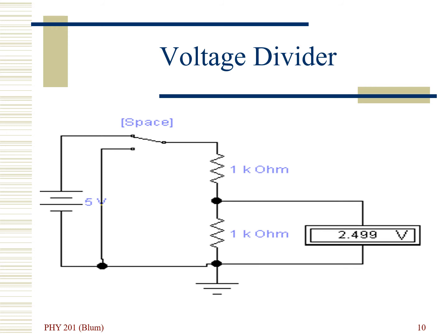We have a 5-volt battery, so we're considering 5 volts to be high and 0 volts to be low. When we connect the switch, which is a digital input, so we're inputting a voltage of 5, a binary digital high input, and then that voltage goes through two resistors of equal value, so that the voltage halfway through is half. And so we've put in a 1, and we're thinking of that 1 as a binary fraction, a 1-bit binary fraction, and a 1 in the halves place, then we would want half of the voltage as an output, and that's what we have.